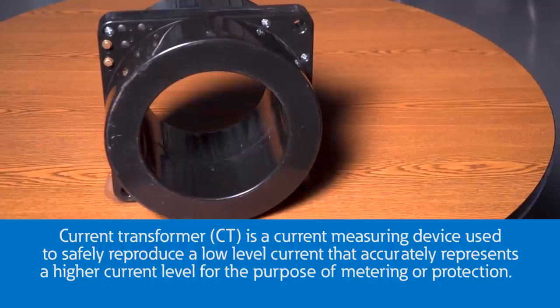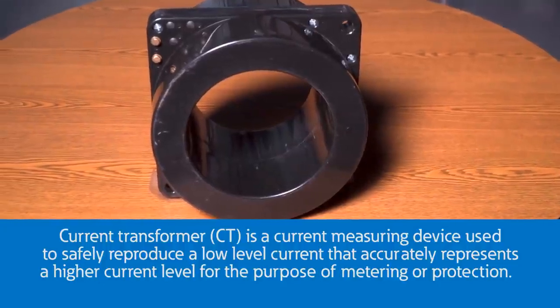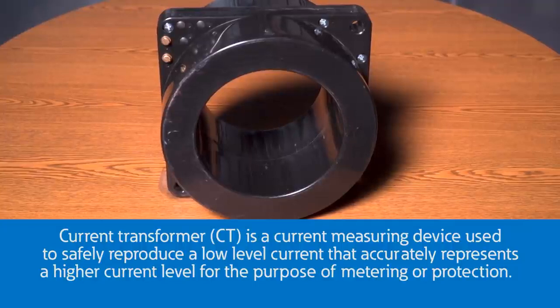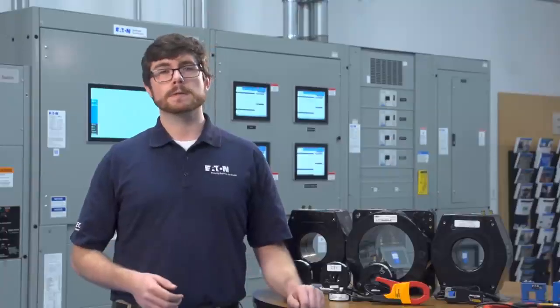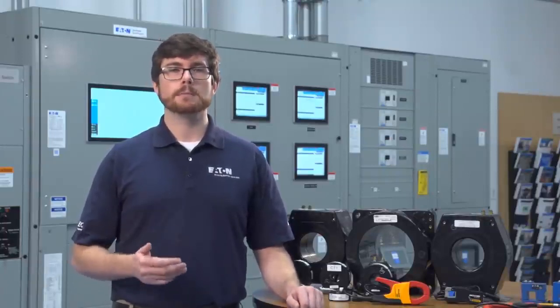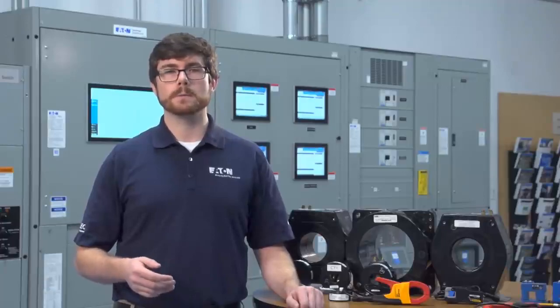Yeah. First, let's back up a little bit and define what a CT or current transformer is. A CT is a current measuring device that is used to safely reproduce a low-level current that accurately represents a higher current level for the purpose of metering and protection. Let's start with a simple explanation that describes the most common ways of calculating and measuring current using current transformers.